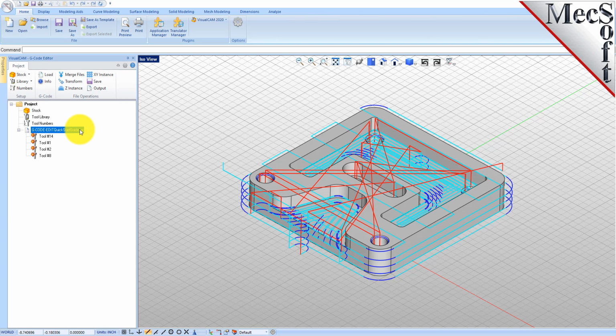That's because in your tool library, you may have multiple tools with the same tool number. In your shop, you may have hundreds of tools, depending on your standards and the way you apply your toolpaths and tools. You may have more than one tool with tool number 1, say.